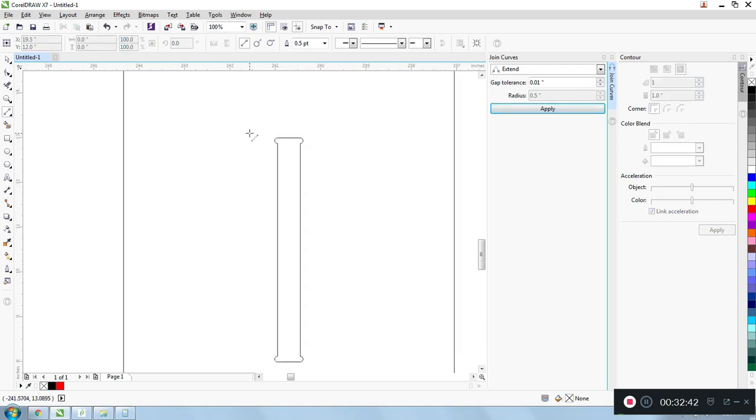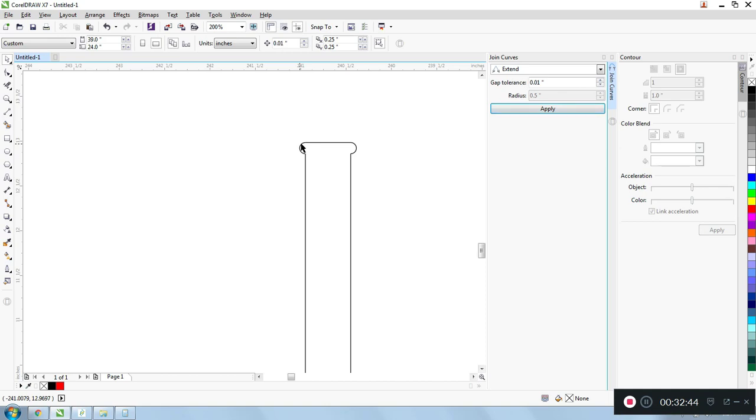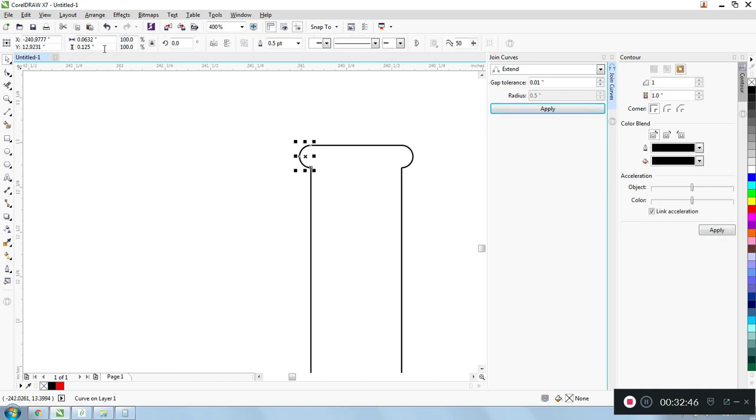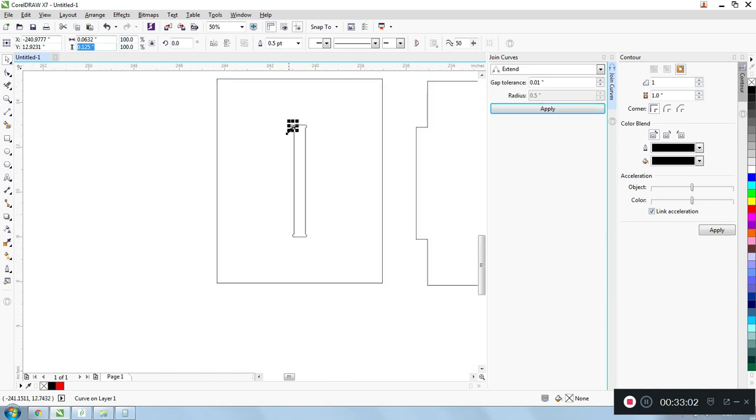So one thing to note, I did actually make this an 1/8 of an inch, which is 0.125. With most CAM software, I would make it like 0.126, 1/1000th of an inch bigger, so that your CAM software doesn't give you hassle about whether or not the bit will fit.